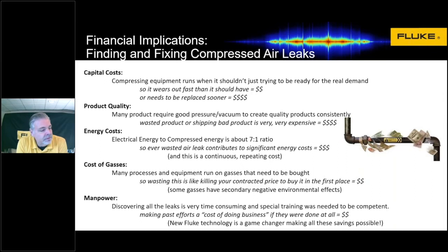The cost of gases, what we mean by that is air, for all intents and purposes, doesn't cost us a lot of money. There may be some drying equipment that would be consumable in the front end of that to make sure that the air is good quality for your tools. But if you are buying other gases, or you have other gases that are being either compressed or delivered through systems that are pressurized, having those leaks happen can be very expensive because you've already paid for that gas. And any contracting that you have to make that gas less expensive will just literally leak away on you.